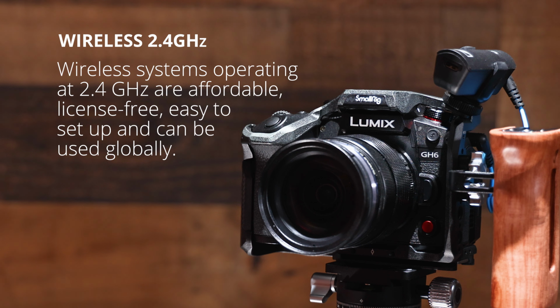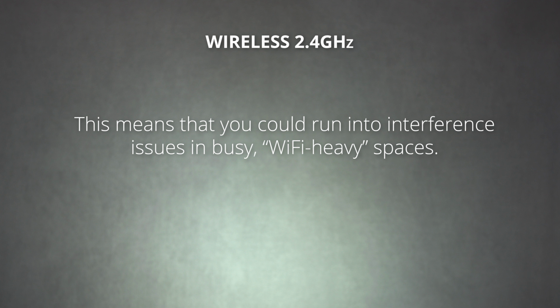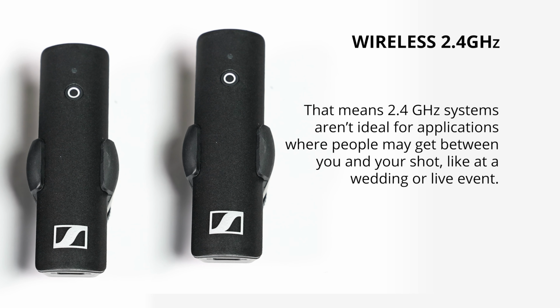Wireless systems operating at 2.4 GHz are affordable, license-free, easy to set up, and can be used globally. However, they share the wireless spectrum with all other unlicensed devices operating in that range, specifically Wi-Fi devices. This means that you can run into interference issues in busy Wi-Fi heavy spaces. Additionally, the signal is more easily blocked when you don't have direct line of sight from the transmitter to the receiver. That means 2.4 GHz systems aren't ideal for applications where people may get between you and your shot, like a wedding or a live event.